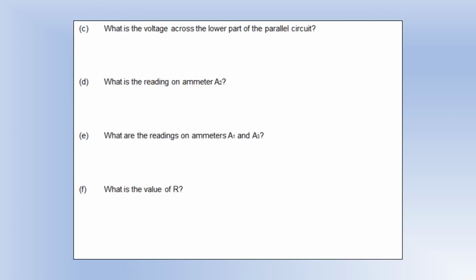What is the voltage across the lower part of the parallel circuit? Well, we can essentially apply Kirchhoff's second law again, so it must also be 16, because it must have the same energy change as across the 10 ohm, is the way I think about it.